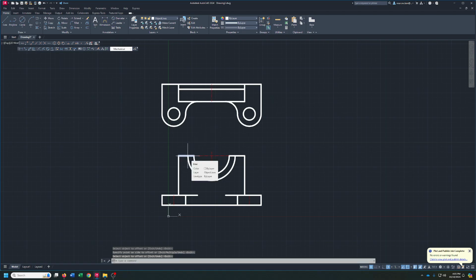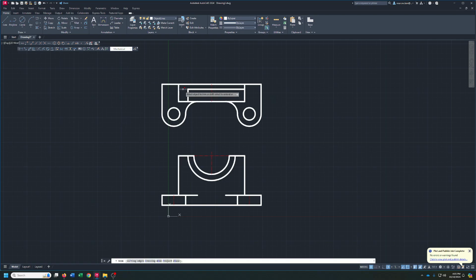And that's going to be where this is at, okay? So we're going to take a line, we're going to start there. Now I'm going to just bring it up until I get my green X and then go back to there. And then I will trim this side off. Now I can grab that line and just mirror it. Remember to hit no and trim this side off.